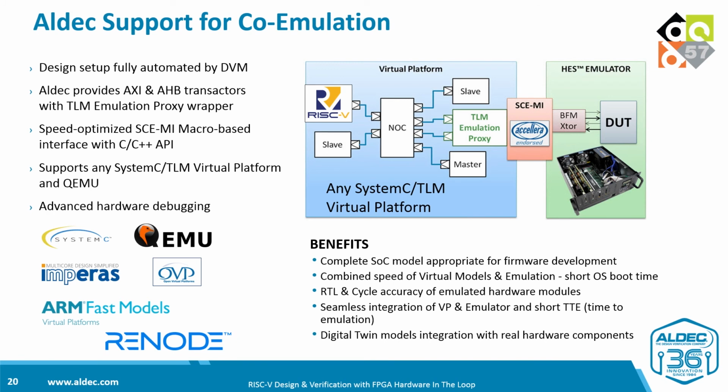Let me summarize a hybrid co-emulation case. If you decide to go with virtual platform, Aldec can provide you extended support of such hybrid co-emulation. Hardware model setup is fully automated by DVM tool, so you don't need to be an expert in FPGA. The HES board integrates with virtual platforms through standard interfaces, and Aldec provides AMBA-AXI and AHB transactors, which are very often applicable in SoC projects.